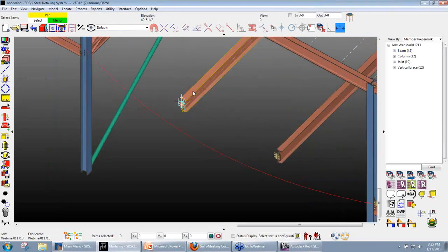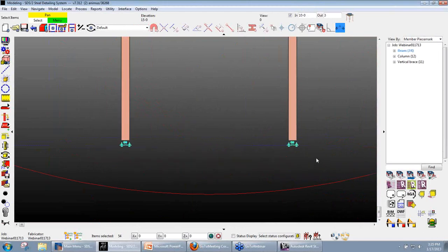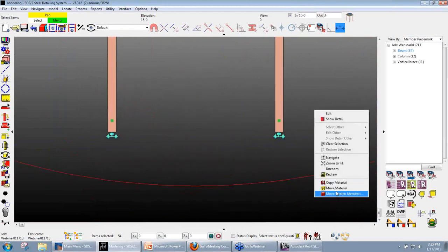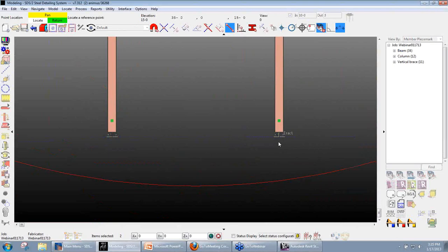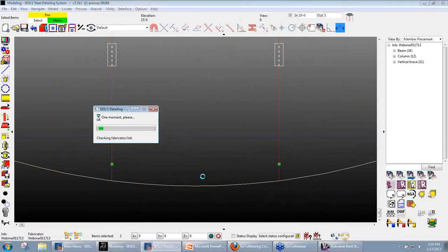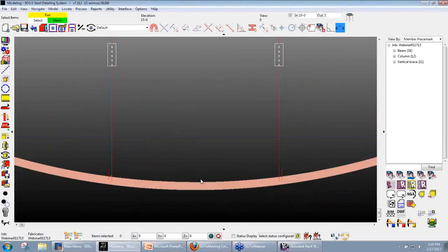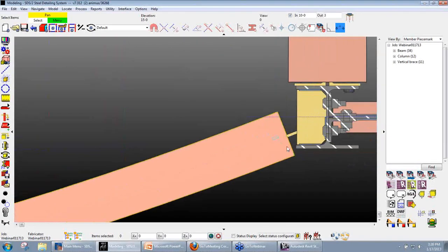I might need to go ahead and stretch these members so that we're framing to the right spot. So I'll move stretch members from exact point to intersection construction line and member. So we get that.